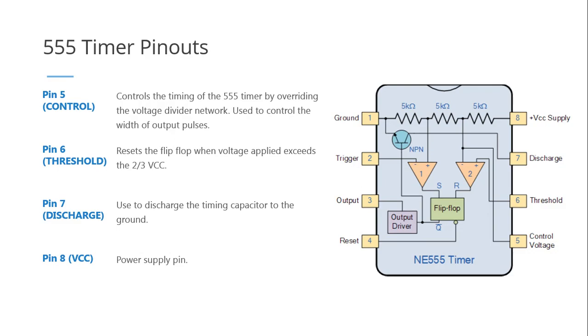As mentioned, we will be having a final, third discussion that would be focusing on some computational requirements for the design of the external circuit of the 555 timer. Of course, we cannot manipulate what's inside the 555 timer. What we can actually change is the values of the resistors and capacitors that we connect outside of the 555 timer.